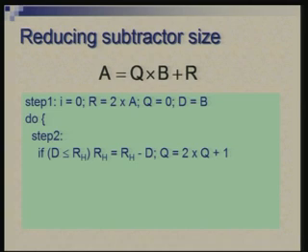We are comparing D with the higher n bits of R. Okay. R is still a 2n bit register, and I am assuming that the two parts, left n bits and right n bits, will be referred to as RH and RL, high and low. Okay. So, now it is RH, or the left half of R, which will participate in this subtraction.